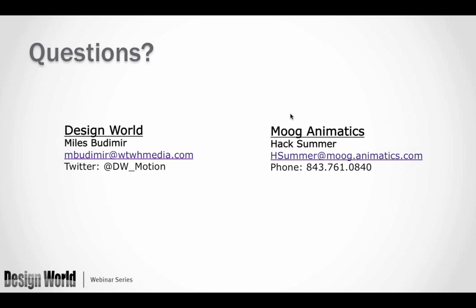Yeah, let me mention a few applications just to give a heads up. We have been outside pressure hulls of jets. We have met specification to be above 35,000 foot elevation, and the low pressure associated with that and low temperature. We've got some HALT tested environment products that have been stored down to minus 65 and cold start at minus 45. We have an external heater connection supplied to those, where you can heat it up to minus 45 and be off and running.